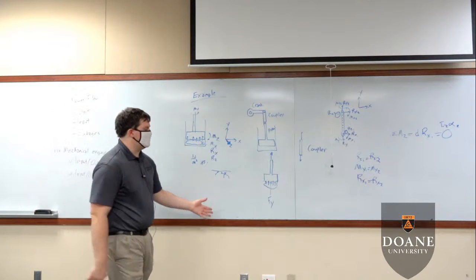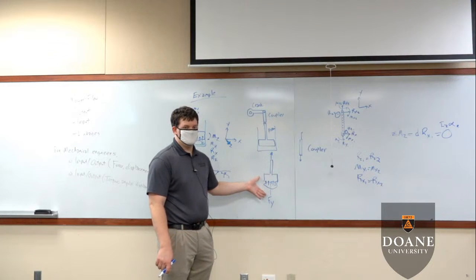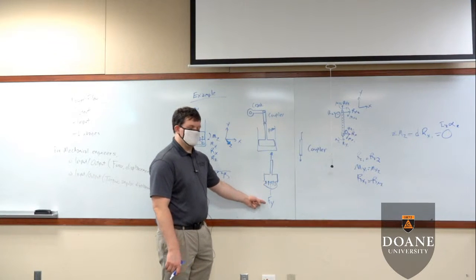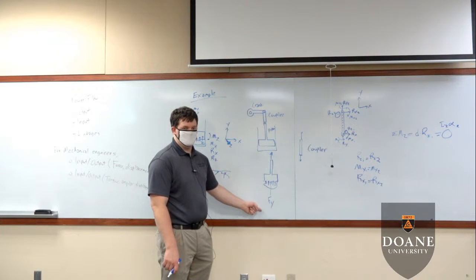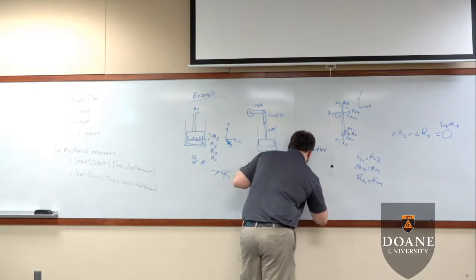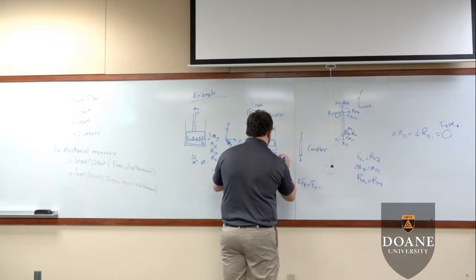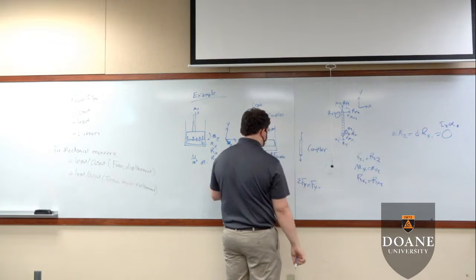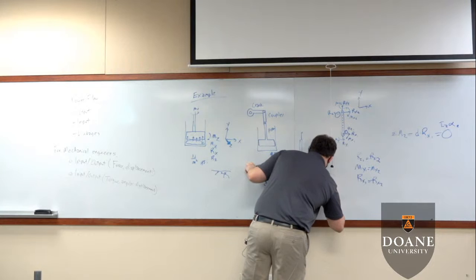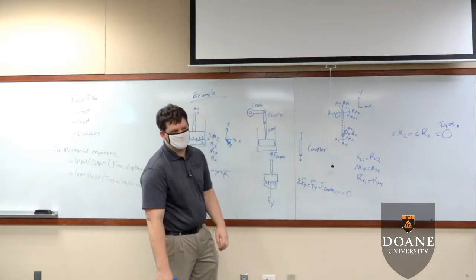Now, just looking at the force transfer here, Newton's second law, the sum of the forces is equal to 0. So here if we sum forces in the y direction, it is equal to Fy plus, I'm going to go ahead and call this F coupler, and we're specifically looking at the y directional component of the F coupler.